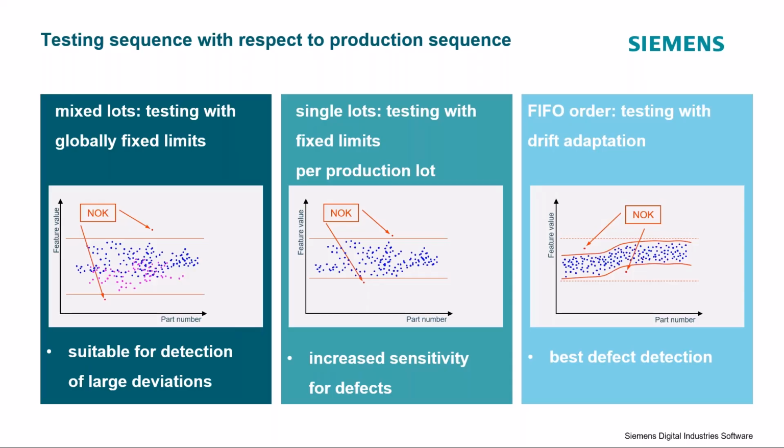The overall scatter in these other cases is a combination of the process scatter and some process drift. And by drift, well, some of the production parameters may drift. Let's say production starts at 6 a.m., 19 degrees in the factory, and at noon they have 24. You might think, well, that doesn't cause a difference, does it? It does. And this is what we see here.